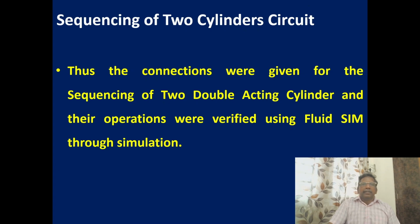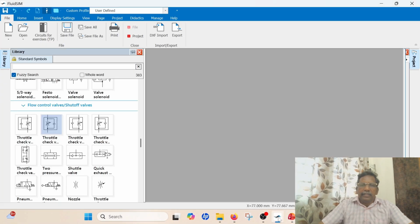So we are going to connect two double acting cylinders, and now we are going to verify using FluidSIM simulation software. Now you can see the FluidSIM software. We open FluidSIM pneumatic software version 6. Go to File and take a new one.